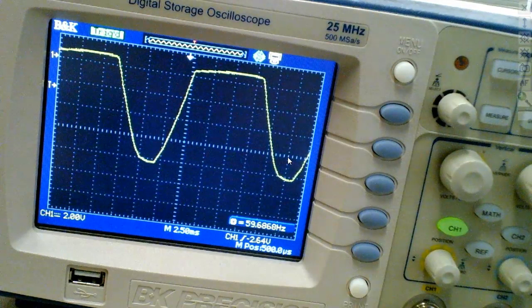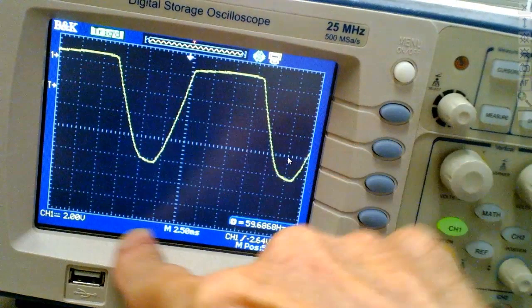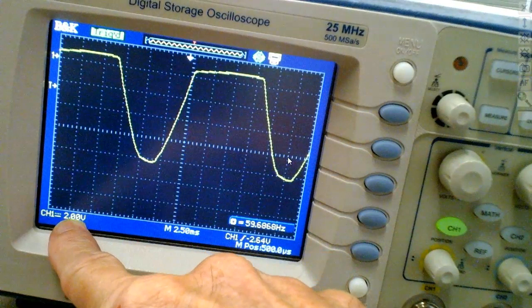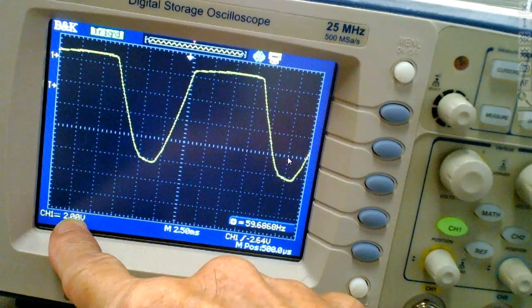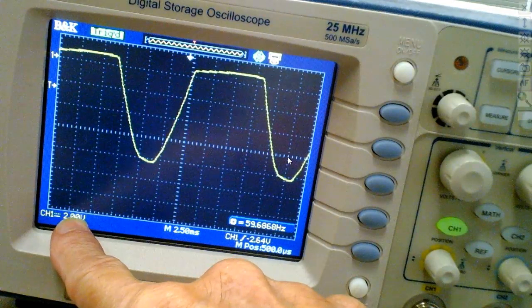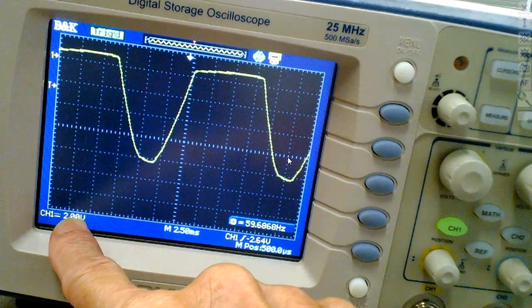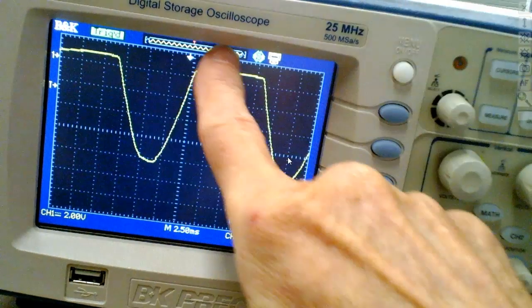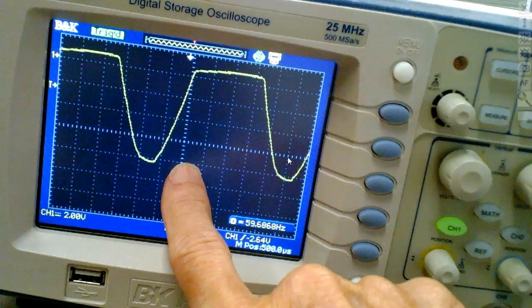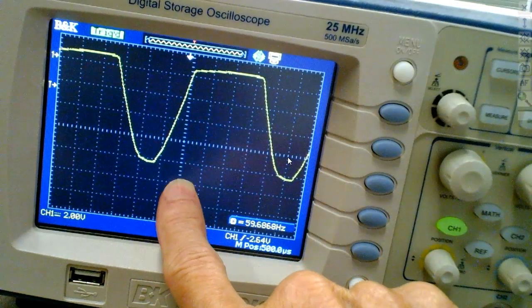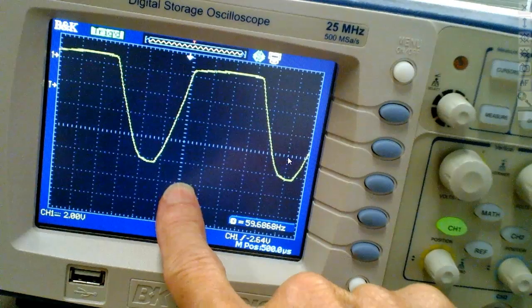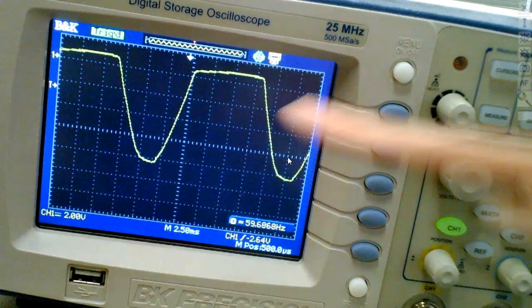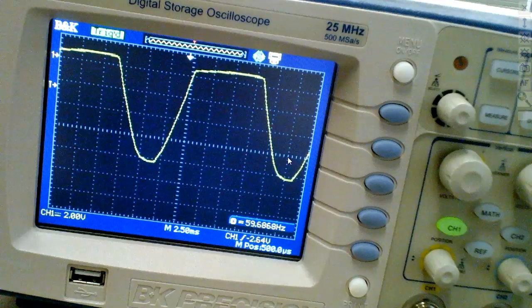So we've got two options when we calculate this. Notice what I did a while ago, because I've been using the scope for a long time: since I had it on 2 volts per division, I just counted in twos, right? Most of y'all can count in twos. If I count in twos, I've got a 2 between this thing right here, and I've got 5 of them, so each minor division would be worth 0.4.